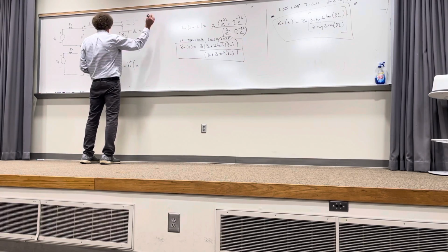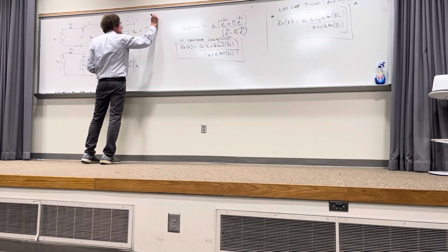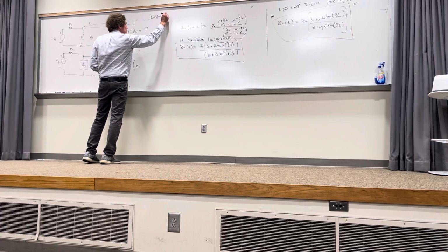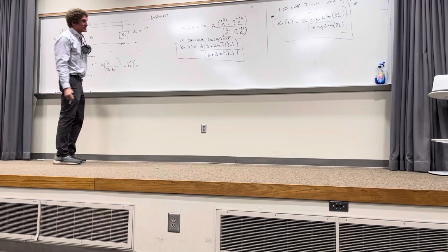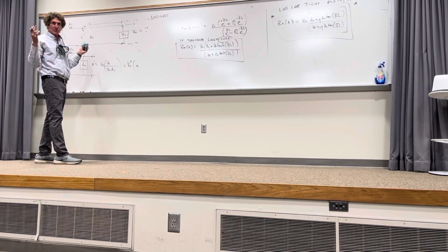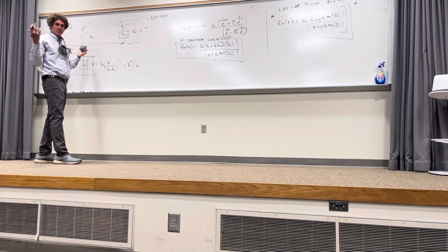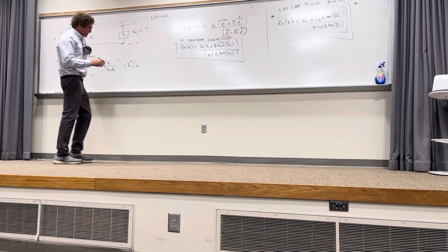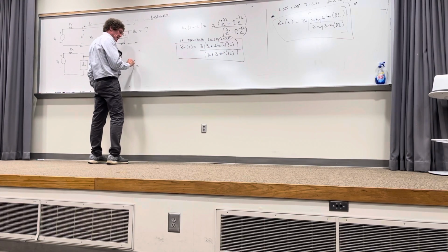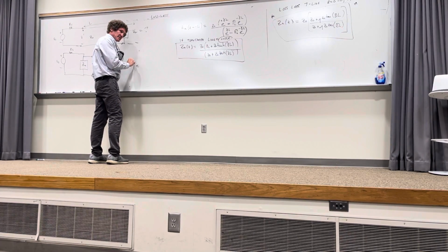I'm going to do this also for the lossless case only. There's no reason to do it for a lossy case. You can, but it's a waste of time because if it's lossy, you're going to redesign it. So here it would be E, and normally it's minus J beta times Z, but Z is minus L. Y'all follow me?